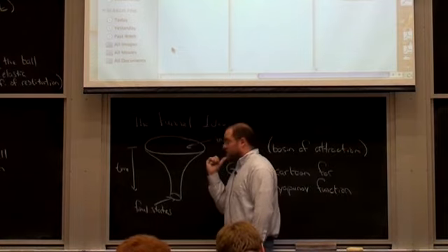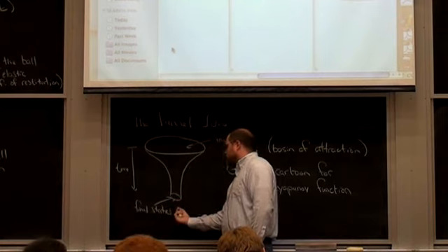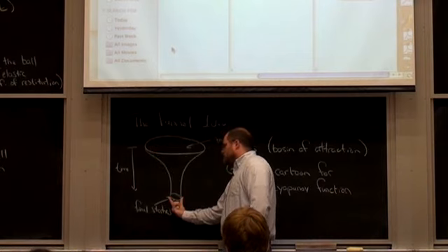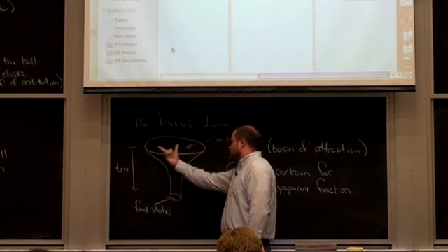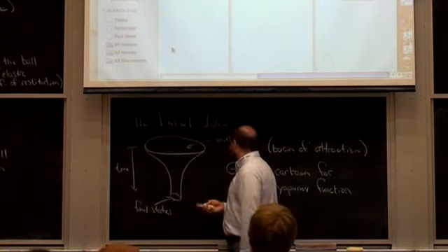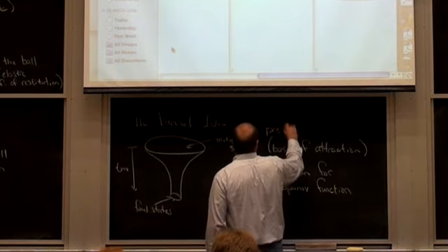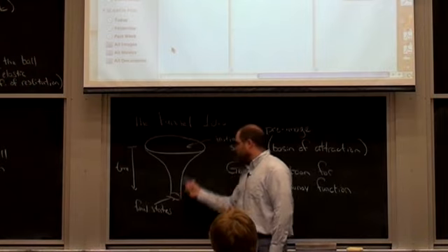So if it was really a basin of attraction and it stabilized to some fixed point, then if I ran it long enough and it was asymptotically stable, I'd call it a basin of attraction. Here I'm just going to run it for some finite time. So you have to be a little careful calling it a basin, but I think it's still intuitive. There's lots of names for this. Another name for it is pre-image in the motion planning world. A lot of people call this the pre-image of our action. It's, I guess, the post-image.